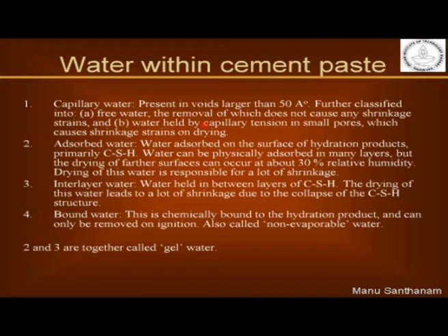So it's needless to add that when you have the gel pores and the gel pores have water inside them, it can obviously be a very high level of shrinkage that can be associated with that. Okay, so gel pore water is usually in two forms. You have adsorbed water or interlayer water.